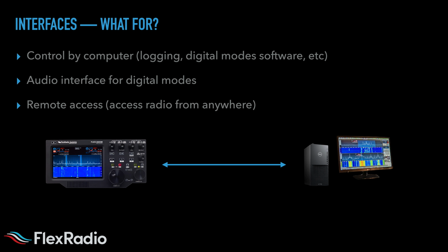You also have audio interfaces, and these are primarily for digital modes, but not exclusively. So the WSJT-X program I mentioned is a digital interface program, and so it produces on-air samples that get transmitted, and then it receives samples from your radio and demodulates those into text. Well, this is true for most digital programs. That's how they work, but you could also be using a contest logger, press a button in it, and have it send CQ for you using your voice because you pre-recorded that and stored it in your computer. So all these types of interfaces use an audio interface typically to your radio.